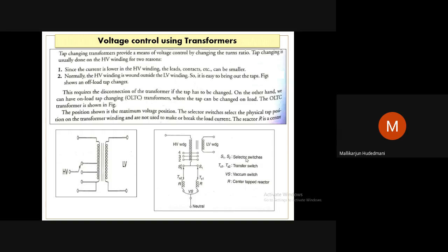Another mechanism shown here is an HV winding, which you can see is a very large winding with several taps, position numbers 4, 3, 2, 1, like this, with a special mechanism, because we have some technical difficulty in switching one contact to the next. There won't be a smooth flow of current. There will be a break of current instead of continuity. So there is a short instantaneous break, a discontinuity and continuity kind of contact. So to eliminate that discontinuity,